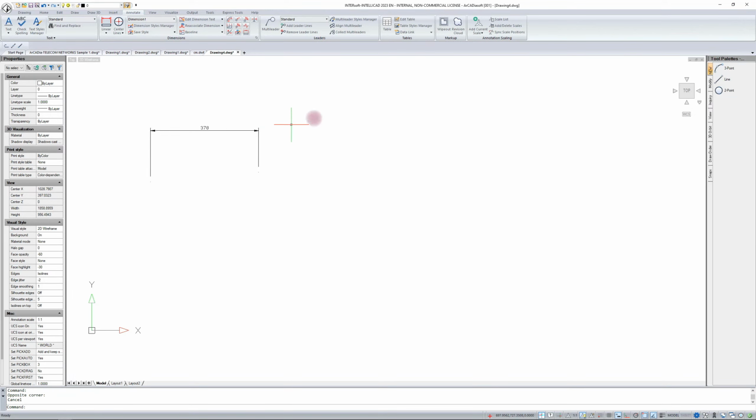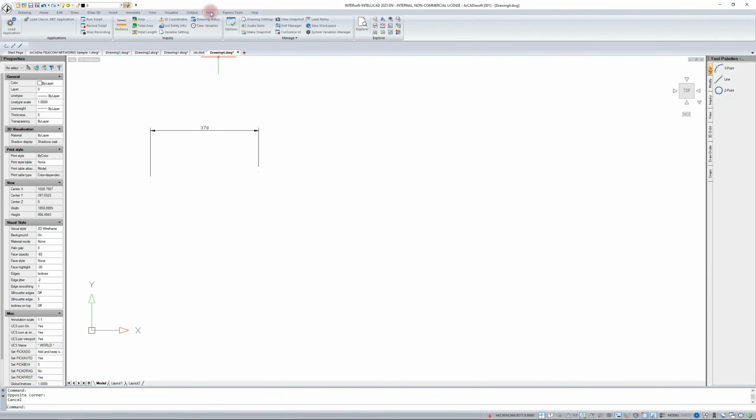Before you actually save this template, you might still be tempted to make some adjustments to the system variables. I've already partially mentioned this before, as I was changing the selection method. The default is that to select something with the area you have to hold down the left mouse button. It doesn't matter whether from left or right, but you always have to keep the left mouse button pressed. I already have it set up so that I click and I don't have to hold the button down because I select with 2 clicks, which helps especially if the drawing, while selecting, we still have to zoom in, zoom out, or move the drawing. Then the held key usually gets in the way.